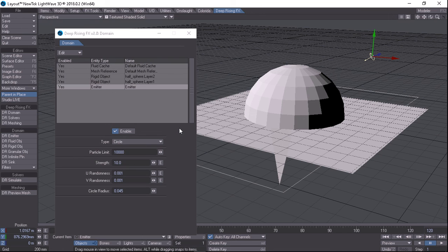So that means you can't have settings like birth rate, because having a value like birth rate, for example, means particles can be spawned at different places, and if they're spawned at different places, they can intersect and the simulation will explode, because SPH is not just a particle system, it's actually a physical simulation. Okay, hope that made sense.